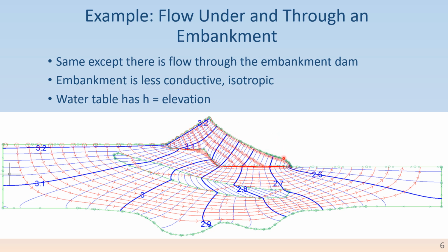And this model took me maybe half hour to an hour to play with that boundary to get it right, or very close to perfect. And that gives me a real nice approximation. Remember, this is just simulating the saturated zone. So this is the saturated part of the embankment. The embankment would continue on and go up higher and then come back down, something like this. And the upper part here would be unsaturated, and we're not simulating that part of the system. We're neglecting any flow there. We're just simulating the saturated zone here.